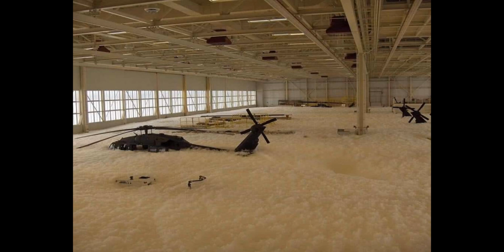What type of handheld fire extinguishers are available for extinguishing interior aircraft fires? Water, carbon dioxide, dry chemical extinguishing agent. How would you determine when the next hydrostatic test is due on a portable fire bottle? Five years from the last test date on the DOT label.